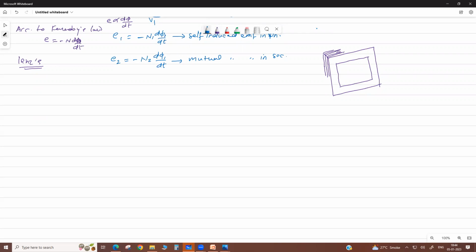So there are two magnetic losses, hysteresis loss. There is one other question also in ETO, earlier asked: losses in transformer. So there is core loss and copper loss. Copper loss is due to the primary and secondary resistance. Got it, my dear? It is I1 square R1 plus I2 square R2. This is the copper loss due to primary and secondary winding resistance. But core loss, or iron loss,